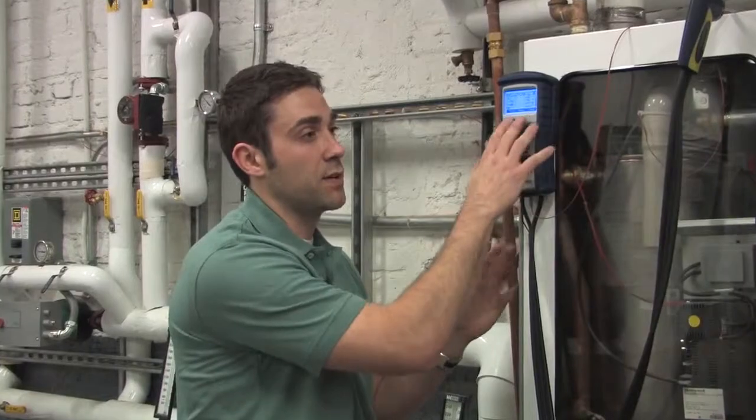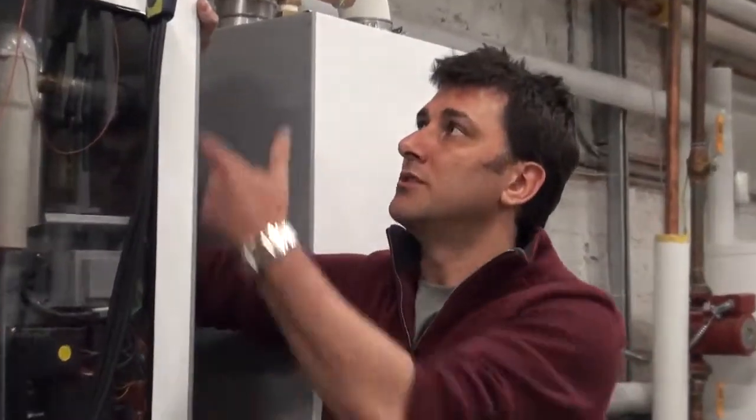So from an owner's standpoint, or a building owner, or a building manager, when someone comes by to service your furnace or your boiler, they should be doing this test, right? Just to make sure that this system is working as efficiently as it can, and there's no problems. You can find out a lot of problems with just these numbers right here on the analyzer. And just because someone sticks a probe in and hooks this up doesn't mean that they're actually reading anything. You should understand what the numbers mean and why. And each manufacturer, in their owner's literature, has the numbers that they would recommend. Right. Where are the adjustments?